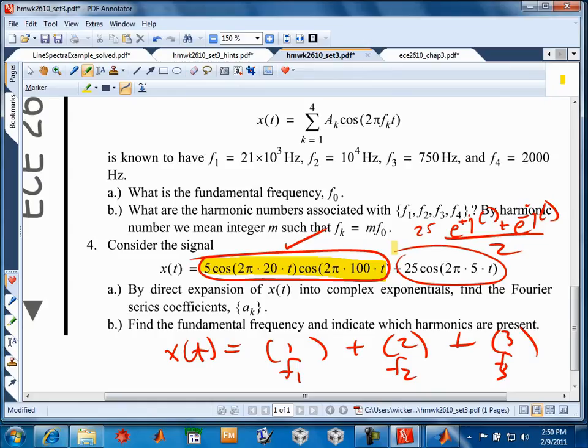So we pretty much have the problem halfway worked now. We have a 5 hertz, we have an 80 hertz, and we have 120. Each one of those cosine waves gives rise to 2 spectral lines, plus and minus frequency, and each of those frequencies, the plus and the minus, has a Fourier coefficient. There's one corresponding to the negative frequency and one to the positive, and there are 3 of them. So the original assessment of 6, do more people agree that was correct, or not so? There's no DC in this case.